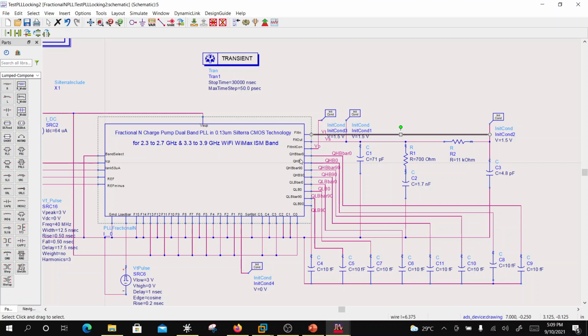I'll tell you what quadrature is. You remember that for a communication system you are supposed to have I and Q, which are going to be modulated by sine and cosine, or orthogonal waves, right? For the higher band you have 0 and 90 degrees, and for the lower band you have 0 and 90 degrees. So for either frequency band you can get the quadrature output.